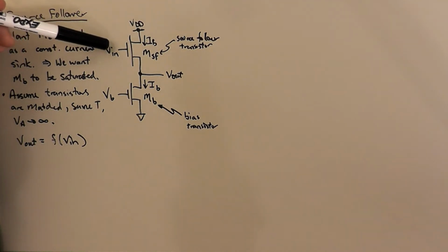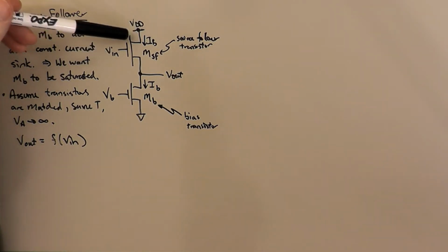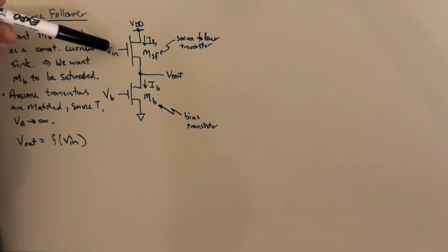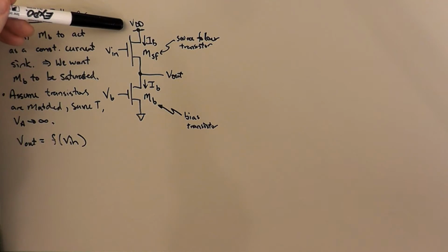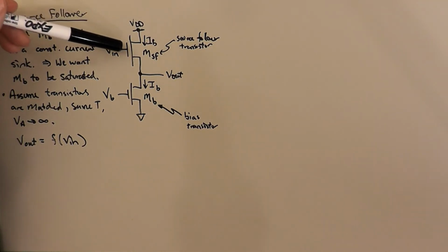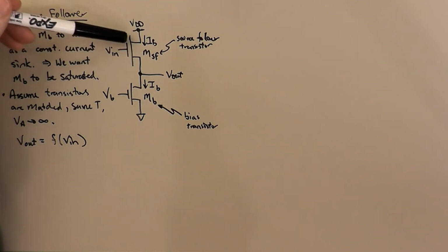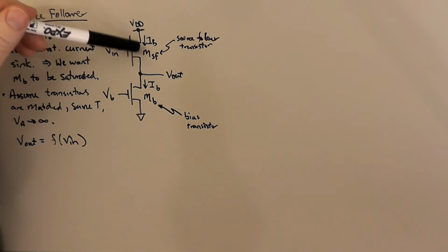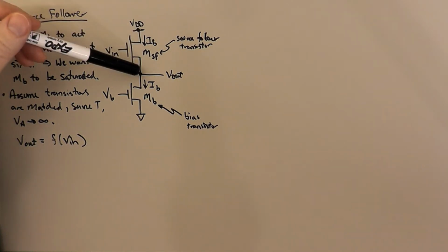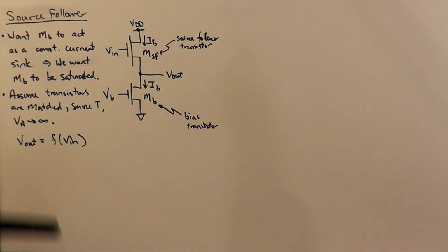It turns out that for a MOS transistor we also have something we call a diode connection, which is when the gate is connected to the drain. And we would have that same sort of situation if Vin is limited on top by the positive power supply voltage VDD. And that again will correspond to the worst case voltage. That'll correspond to the least voltage across the transistor, and so worst case with respect to the transistor being close to the ohmic region.